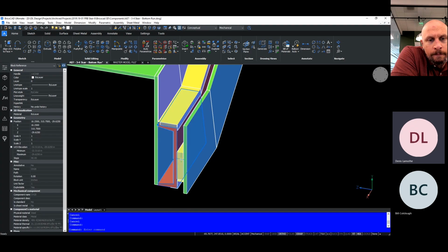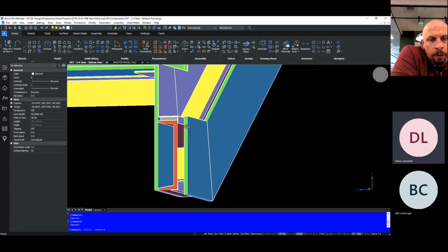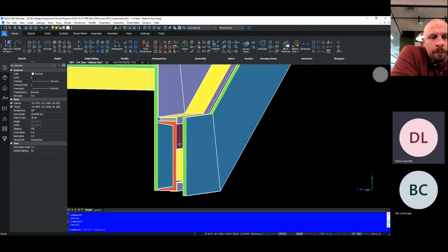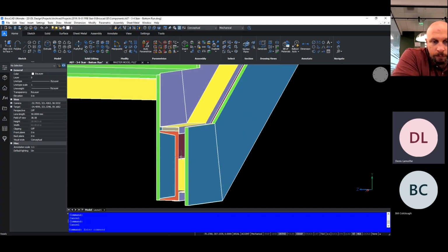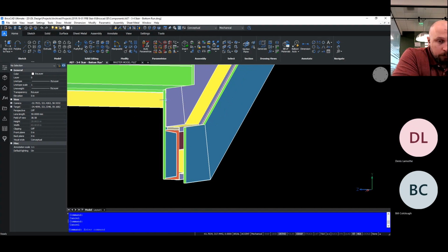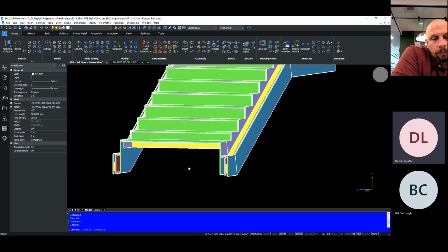And we had a flat bar and then another plate. This one would be stainless steel, and this would create a pocket on the inside that we could slide a glass panel in to install our glass railing. So we didn't need a separate shoe. It was built into the system. So this whole assembly came on the site as one big component.